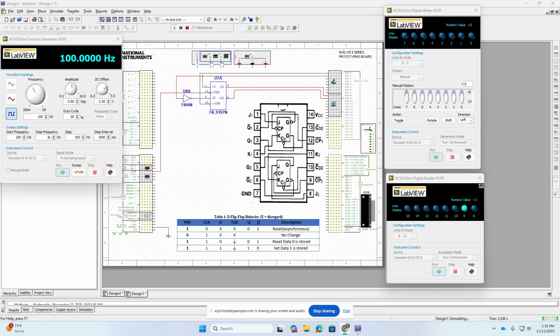So what you do, if you want them to function as a D flip-flop, you connect the J inputs together. And the one condition is that the J and the K always have to be opposite of each other. That is the reason you see the inverter there, to ensure that J and K are always opposite. Then it'll run in the D flip-flop mode. Again, we could have done this with the 76, but on the image on step 5, they're using the 107, so I went ahead and just created this demo with that.